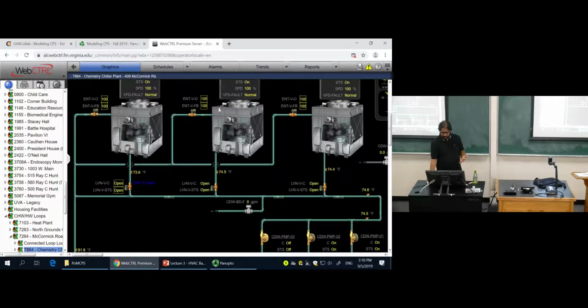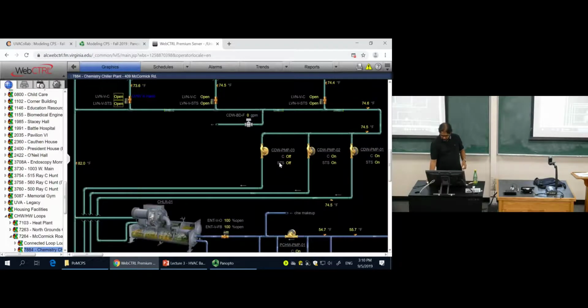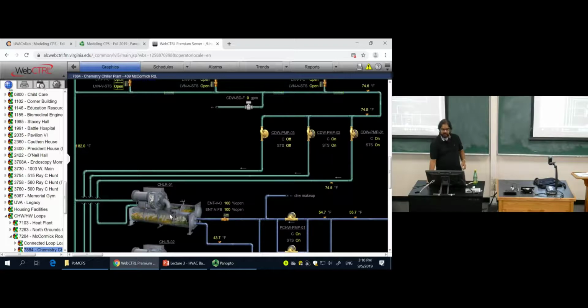The mist is getting created. And from 82 degree Fahrenheit, we are receiving 73 degree Fahrenheit water back. So we have rejected that thermal mass to the environment. And this 73 water is getting sent back through these pumps into the chiller again, where it's going to get back to 82 because it's rejecting this heat from 55 to 42.